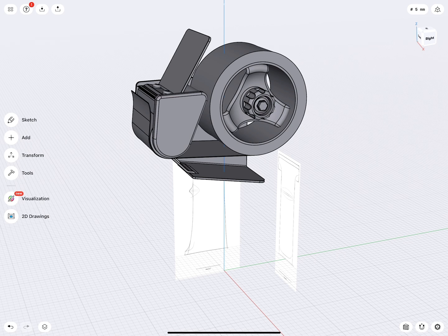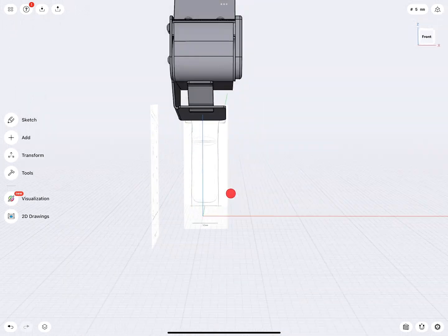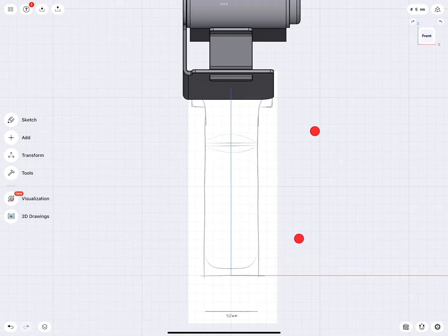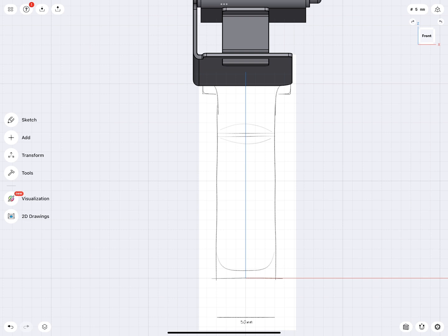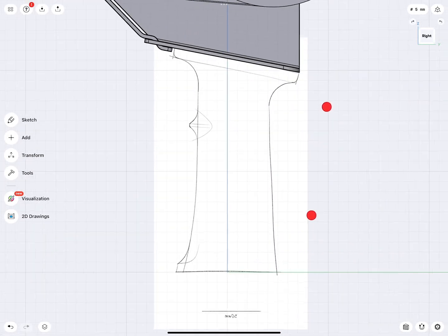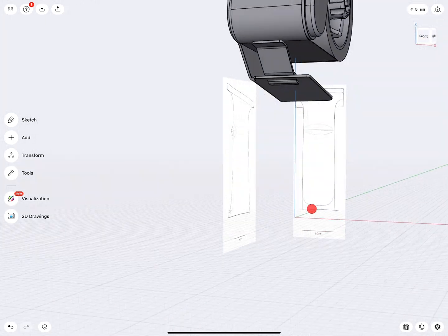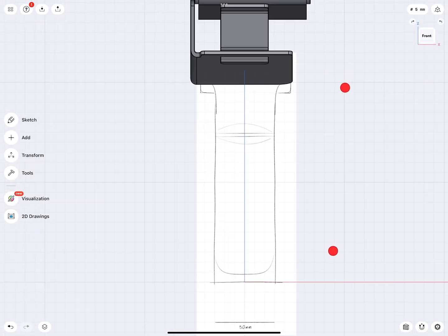And to guide the designer, we have a side and a front sketch. The sketches are positioned, so they are in the background. They are also scaled, so I can use those not only loosely as a reference, I can literally sketch over them. The sketches are also created very carefully so that dimension-wise or detail-wise, these elements are all at the same position.